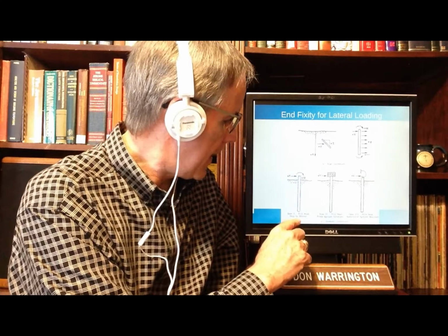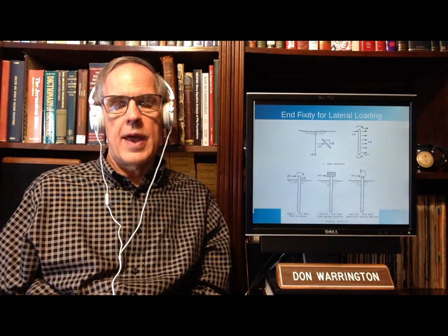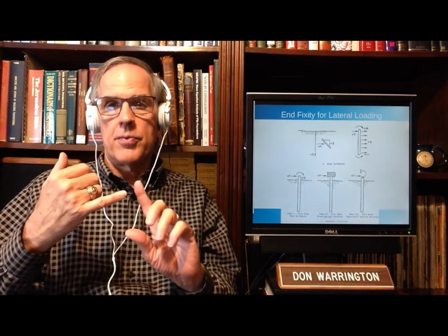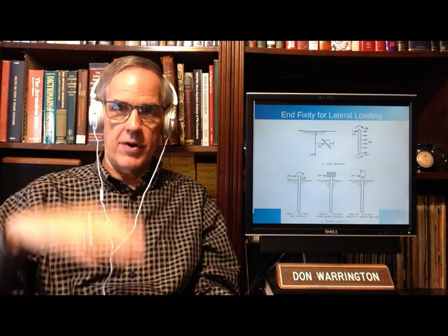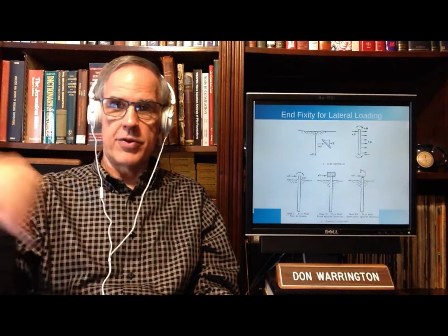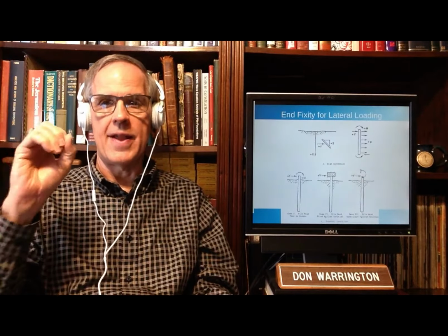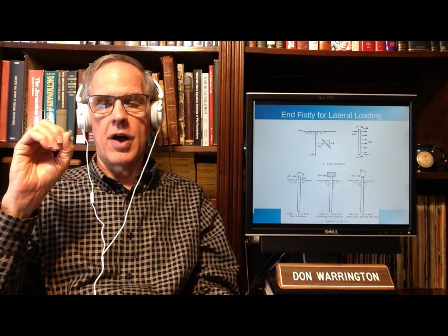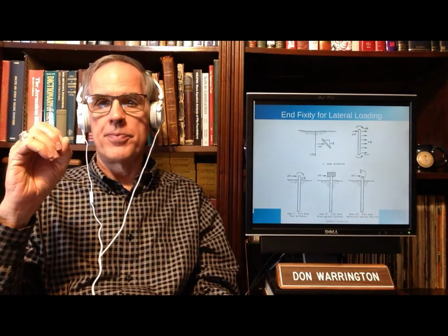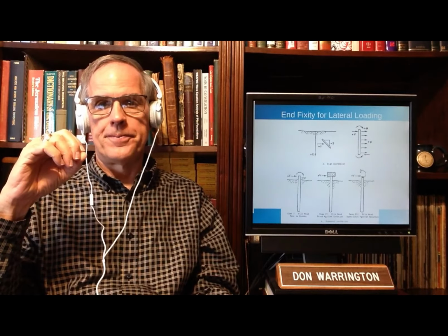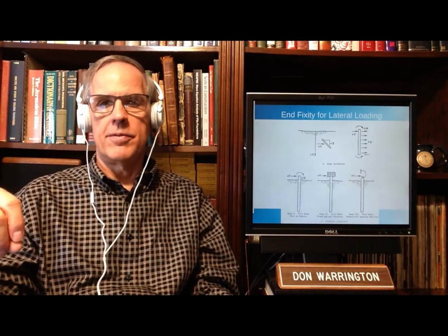One of them is the pile head is free. Basically, the pile head is free in all directions. In other words, it can move horizontally, it could move vertically, obviously for axial loads, and it can also rotate. It's completely free to rotate. So that's a free head. And although we would normally associate a free head with something like an offshore wind farm, there are other conditions which can be said to simulate a free head.